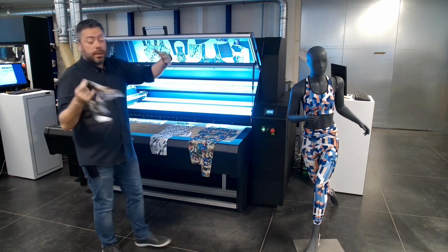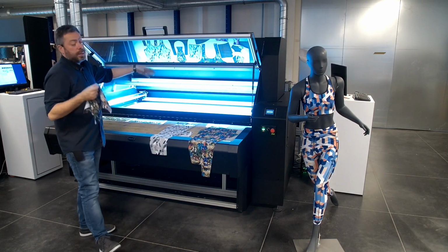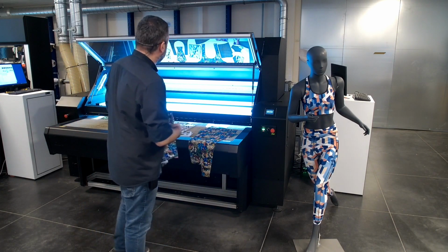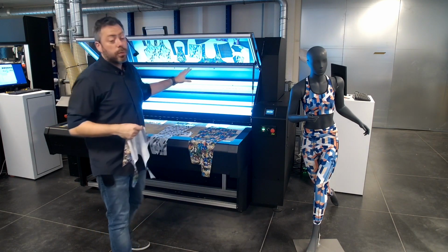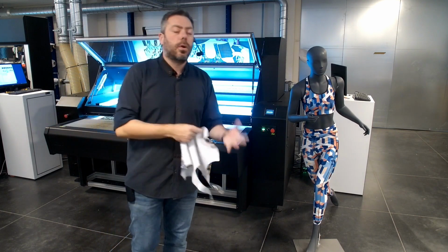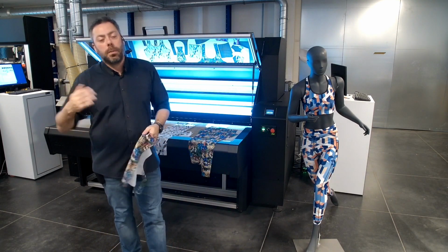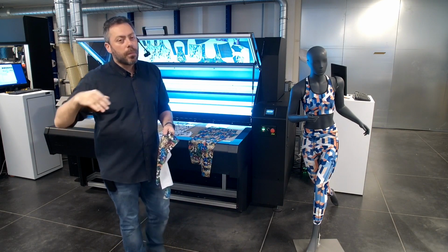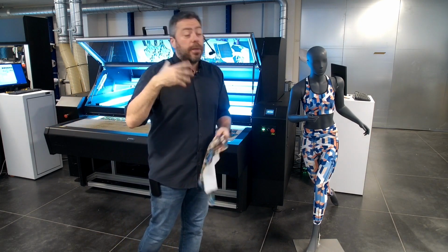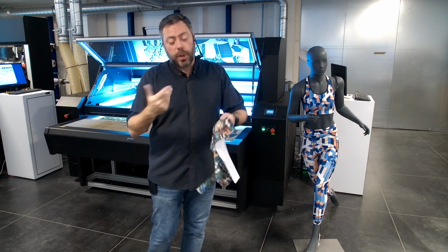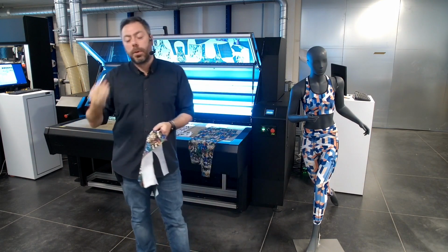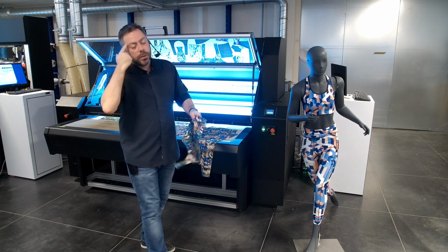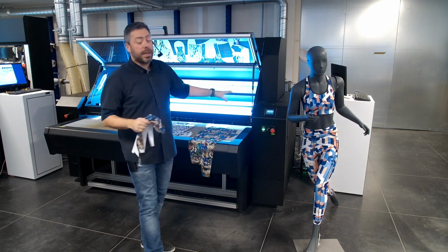The laser tube that is in here is a metal tube laser, so a high quality laser tube. At the moment it's a 100 watt air cooled laser. We do offer water cooled lasers as well, but the water cooled lasers are generally higher powered. And if you're not acquainted with the laser technology, the more power you have, the more potential cutting speed you have. But you still need to take into account the limitation of the machine.